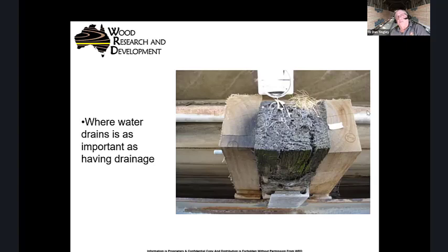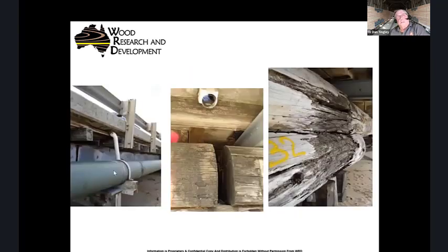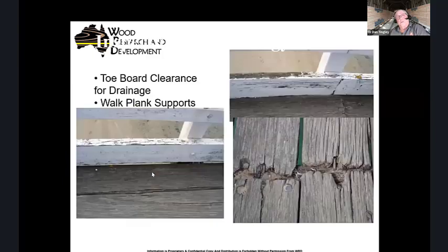And the whole time, for $2.49, they never bothered putting an extension on that drain to keep the water off it. So it's not timber's fault. And here, on the same bridge, they didn't want the water to get on a galvanized pipe, so they put the extension on it, but left it off every place there was timber. See, that's not wood's fault.